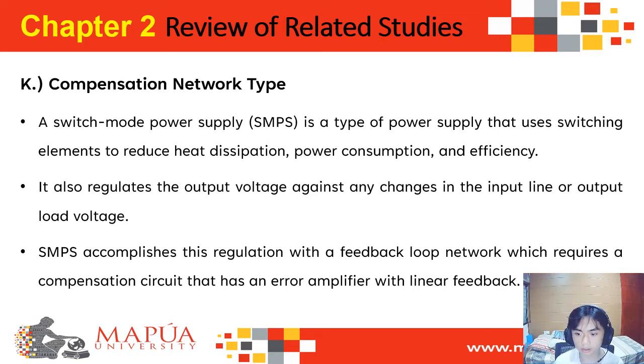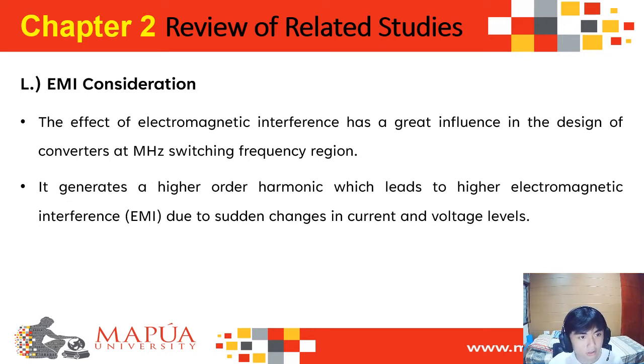So next is the EMI consideration. The effect of electromagnetic interference has a great influence in the design of converters at the megahertz switching frequency region. It generates a higher order harmonic which leads to higher EMI due to sudden changes in current and voltage levels.